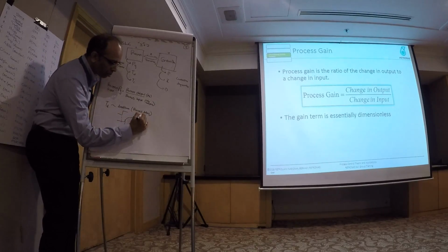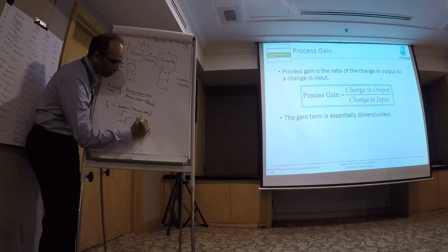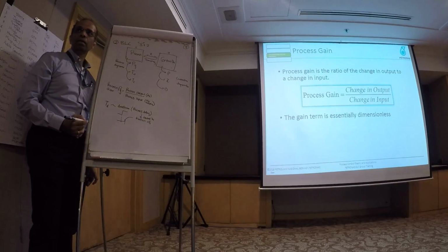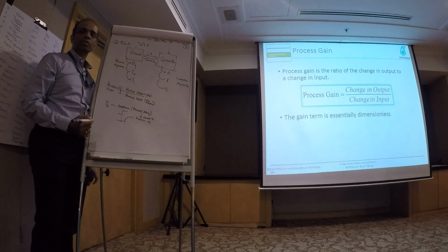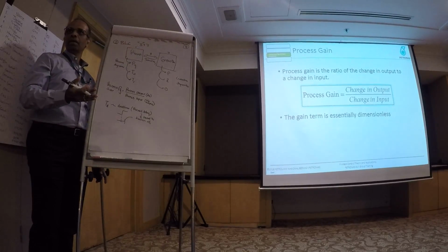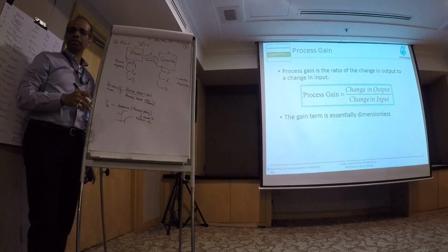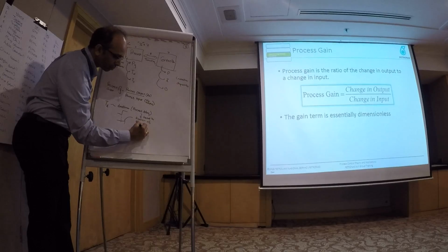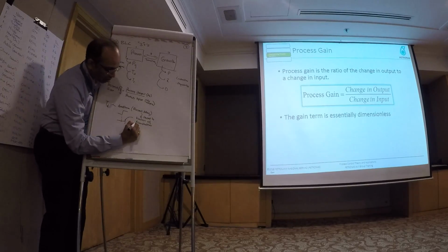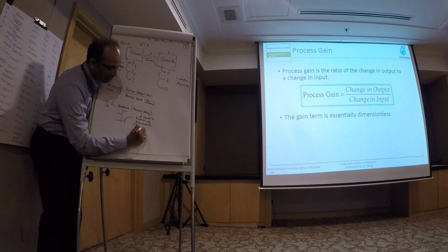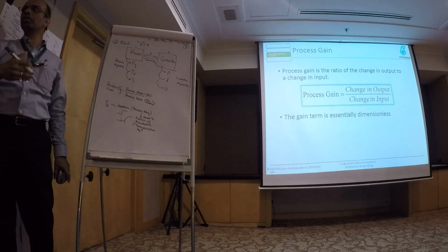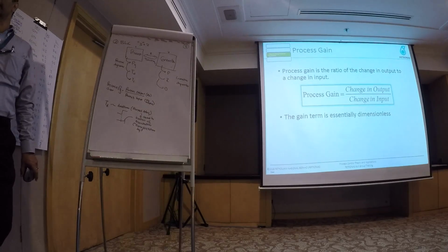And it is usually associated with location, caused by location of the transmitter, right? Because usually we don't put a transmitter inside the furnace, we put it outside. So the furnace gets heated up, but the process fluid has to reach the transmitter, right? So location of the transmitter, which is why another term for dead time is transportation lag, because it needs to be transported to the transmitter. Okay?